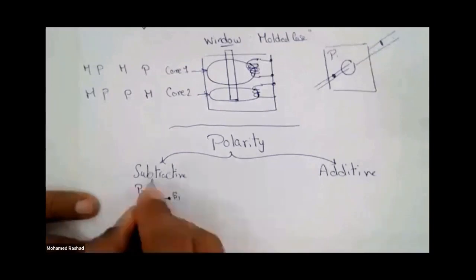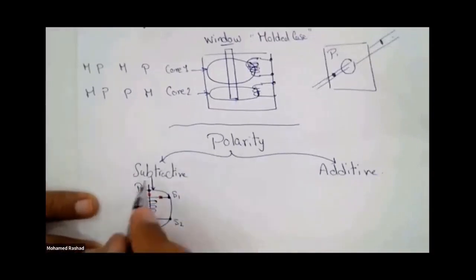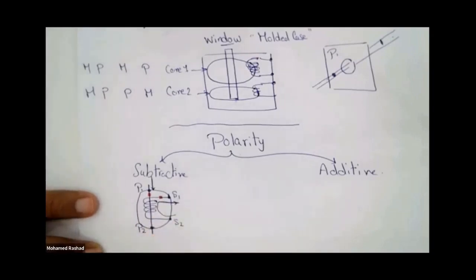This means the direction of the current. If the primary is going in, of course, this is closed on it, right? So if the current is entering the dot point of the primary, it exits here from S1, meaning it goes like this in the S2 circuit.